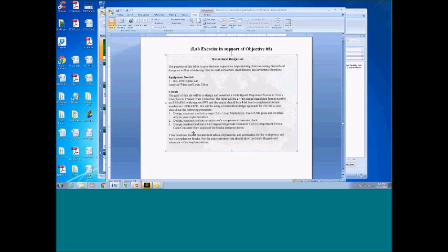Basically, it had to determine if it was a positive number or a negative number. If it was a negative number, you had to do the 1's complement and add 1 configuration. So you fed it through a mux to determine which way it was going to go: if you were going to add it directly, just regular addition, or do a signed addition for negative numbers.